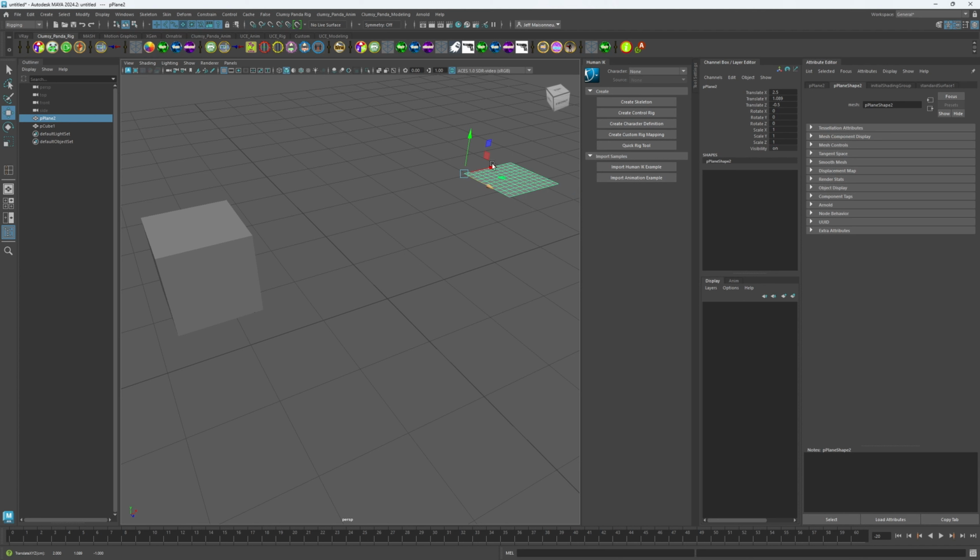If I want to reset my axis, I can hit the W key, or if this one's already activated, I can just click right in the middle. That will reset my axis. So now if I press X again and I wiggle, you'll notice that now it went back to where I wiggled. So X, middle click, wiggle.